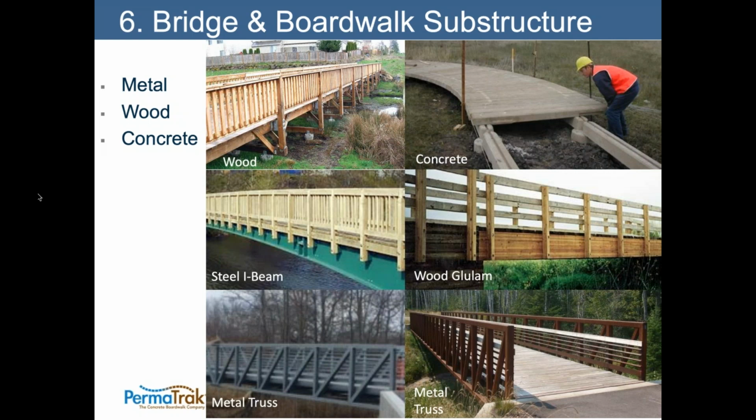But it's important to understand, if you're designing the structures, what the limitations of those materials are. For example, with the wooden systems, if you're looking at that picture in the top left-hand corner, you see that the supports are generally close together. So be thinking about what that means to you as a designer or the owner. You're going to see more piers, and I've commonly seen anywhere from 6 to 10 feet of spacing between the piers as you travel down the boardwalk.